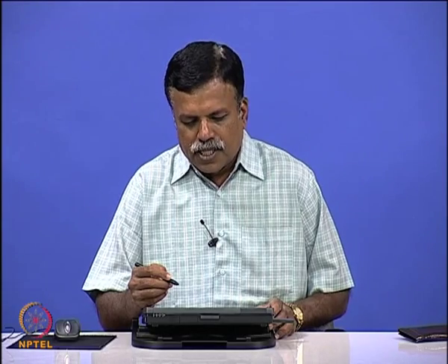So, in this class we showed what errors come in the temperature indicator circuit. We showed 3 errors: one is drift due to the Zener, another is offset voltage drift error, and the third is resistance drift error. We showed how much the total error was when these 3 errors are put together, and also how to reduce them. We also discussed various resistors and their characteristics, and we discussed a little about capacitors.